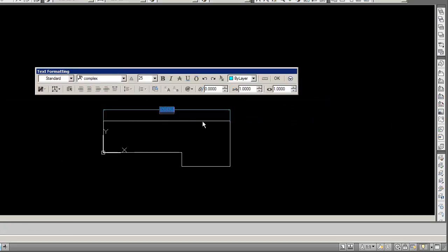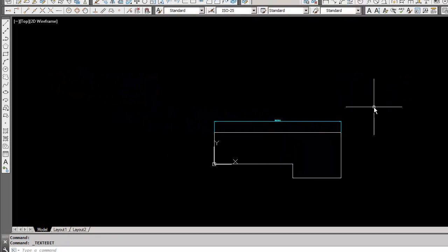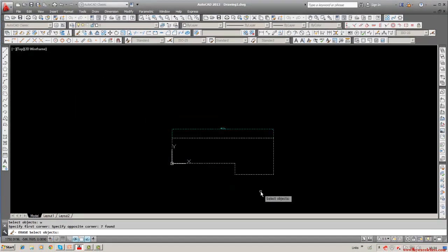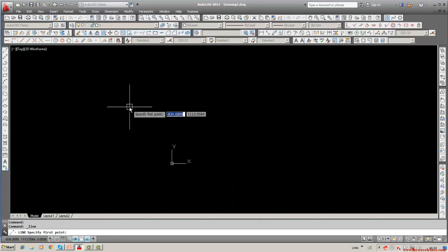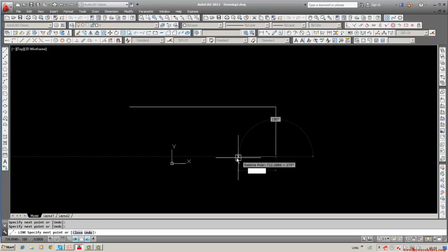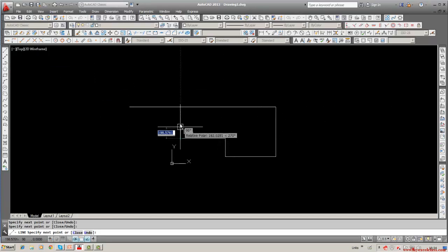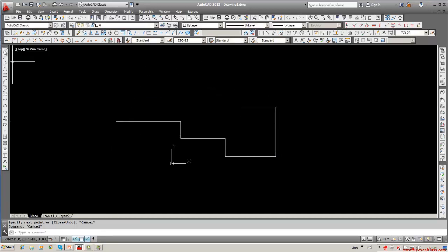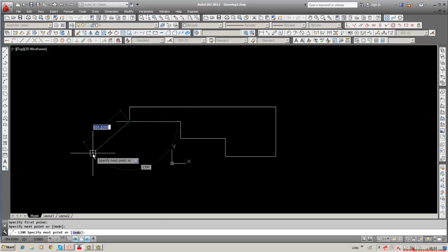Suppose the line is not drawn to scale. So then you can edit it, suppose I want this to read as 3000 mm. That means it has to be 3000 mm size. When you manufacture, the length should be 3000 mm. I will erase this. I will draw once again. This we know, linear dimension. Now, we also know something about other dimensions.